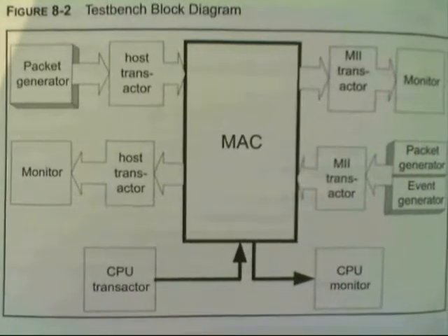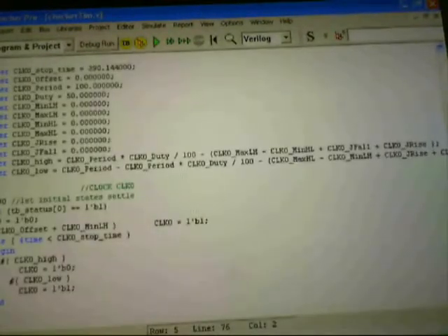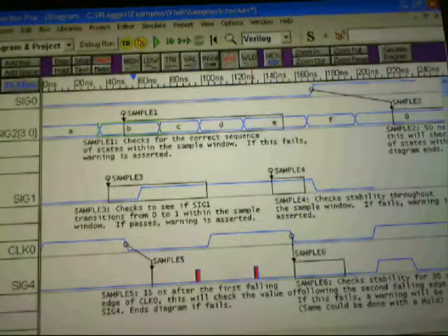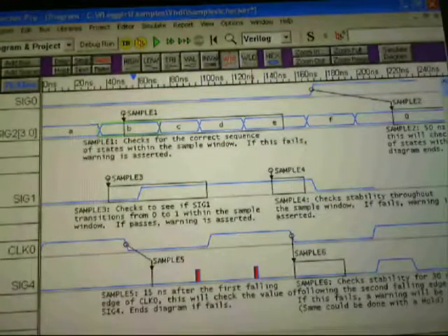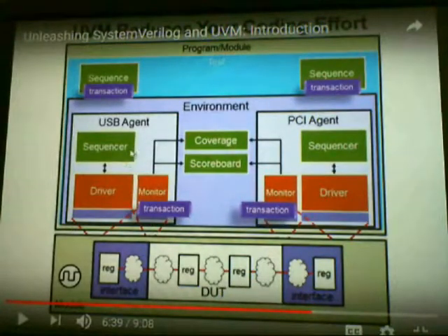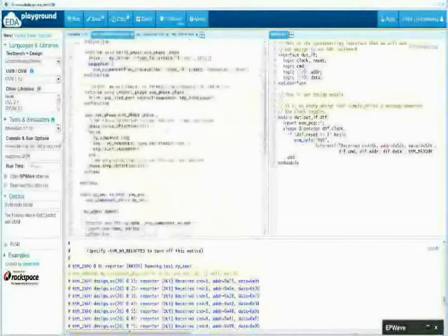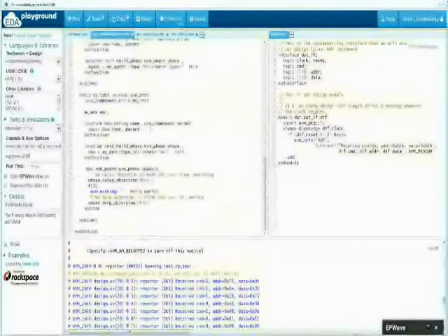The network events include collision. The MAC test bench sends packets in full duplex mode, produces random number generator functions, provides polymorphism, supports cycle accurate reference models, and also semaphore registers. There are two main types of formal verification, that is model checking and equivalency checking. In model checking, the verification engineer writes invariants for the DUT, design under test.